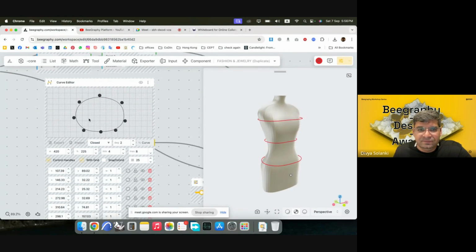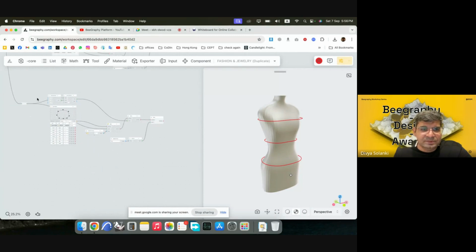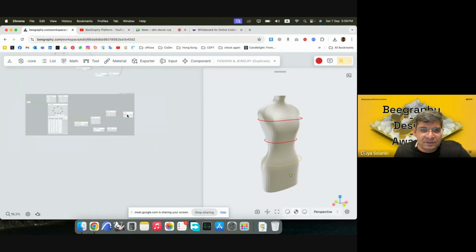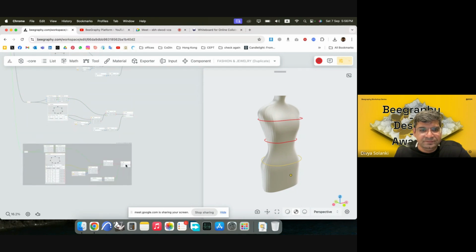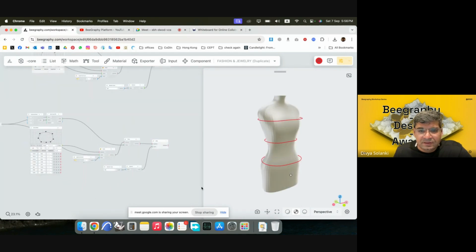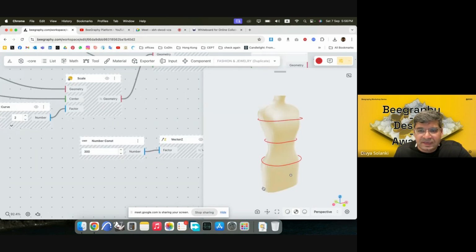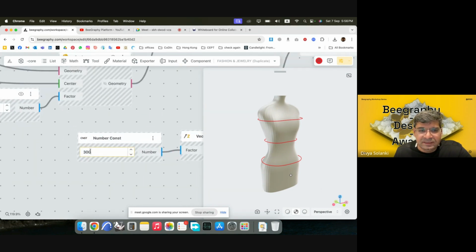The next thing we can do is for the lowermost part. So I'll copy one more time. And this time I will try to rotate the base. I'll take this down to 0. My mannequin actually starts at the grid point, so it's supposed to go up, but it could change as per your subject.